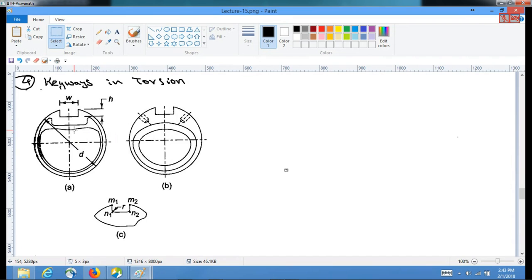The inner contours are deflected less, the outer contours are deflected more, because we know that in the shafts the outer layers take highest stresses. That's the reason we also go for shallow keyways. Anyway, we'll come to that at a later part when we are designing shafts in the coming sections. Now, in order to reduce this stress concentration or abrupt changes in this manner, there are two ways. The first thing is to drill holes inside this shaft so that it would deflect the stress lines.